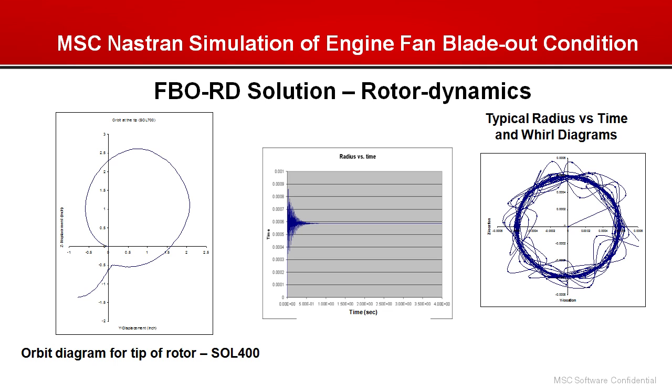SOL400 has the same rotor dynamics capabilities as the legacy solution 129. Some of you may be familiar with Nastran rotor dynamics solution, but it's even more powerful. So it can be used to generate the whirl diagrams or the orbit diagrams and the time histories of interest.